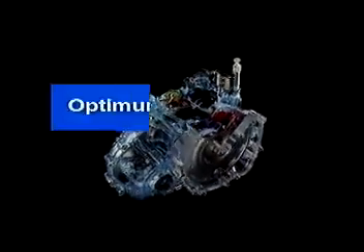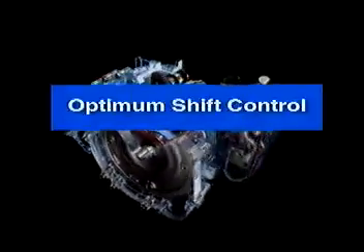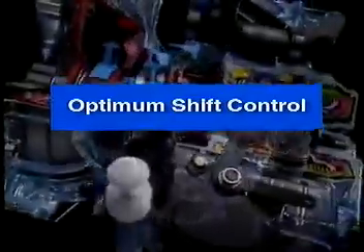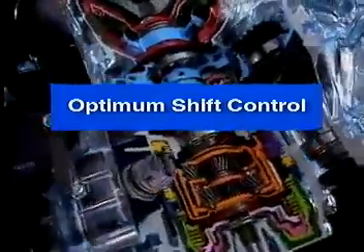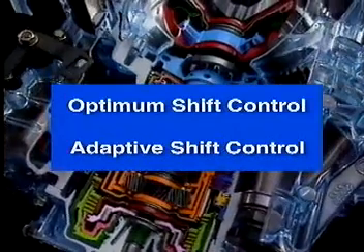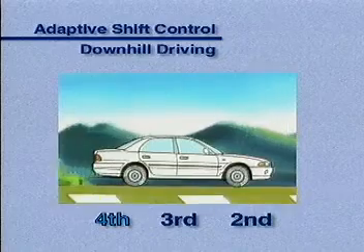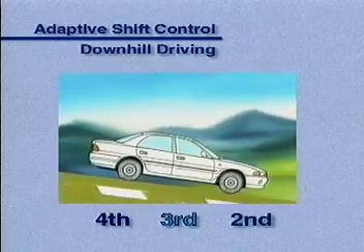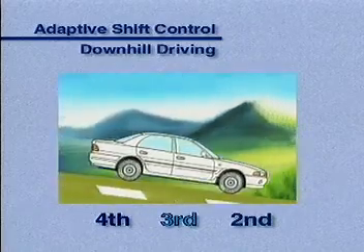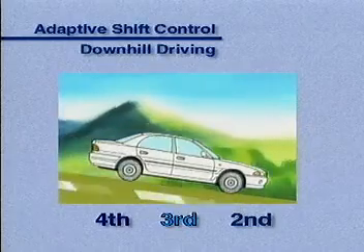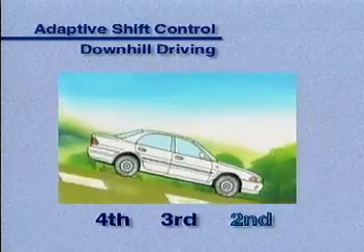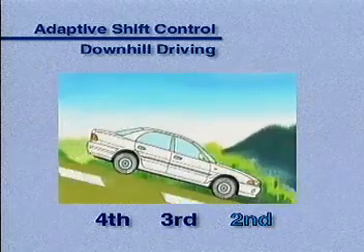To provide the ultimate in driving comfort and precise control, fuzzy logic transaxle control that has been used with other Mitsubishi transaxles has been expanded with a new, intelligent and innovative electronic control system, or INVEX 2. With fuzzy logic, the transaxle modifies its shift behavior when traveling up and down hills as a result of driver inputs such as throttle and brake pedal application and vehicle speed. However, fuzzy logic is unable to sense the driving preferences of a particular driver.